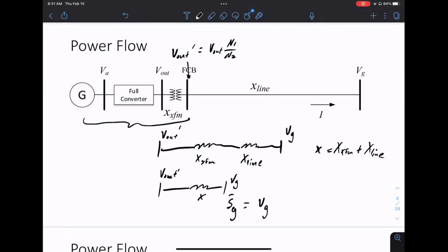Again, this is Vg times current conjugate. So this is P plus jQ. Right? Any questions? So one thing again to remember is for type 1, 2, 3, the resistances in the lines are important. You cannot actually have an induction machine without a resistance on the rotor. The rotor resistance is important because it's a R/S divide. Okay? Here we don't care anymore because there's not a R/S.